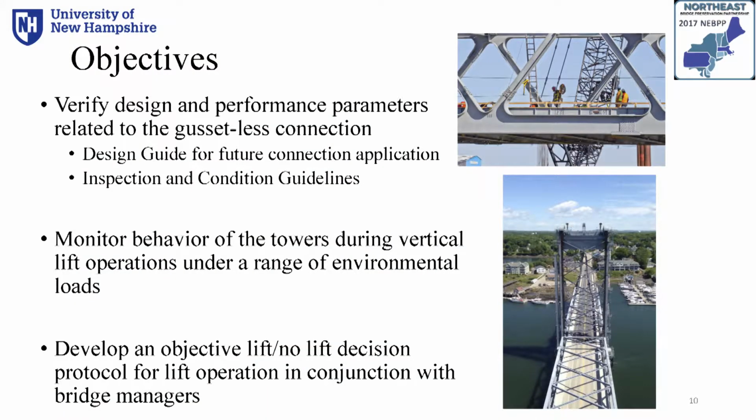The main objectives of this study are to verify design and performance parameters related to the gussetless connections in this bridge, monitor the behavior of towers during vertical lift operations under a range of environmental loads, and also develop objective lift or no-lift decision protocols for lift operations in conditions with bridge managers.